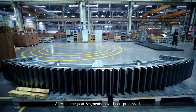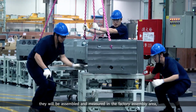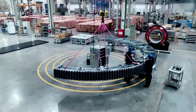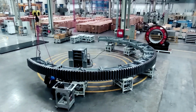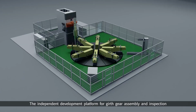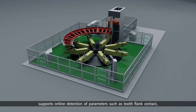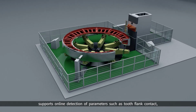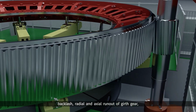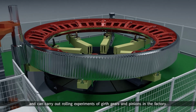After all the gear segments have been processed, they will be assembled and measured in the factory assembly area, which will ensure the accuracy of the overall size. The independent development platform for girth gear assembly and inspection supports online detection of parameters such as tooth flank contact, backlash, radial and axial runout of girth gear, and can carry out rolling experiments of girth gears and pinions in the factory.